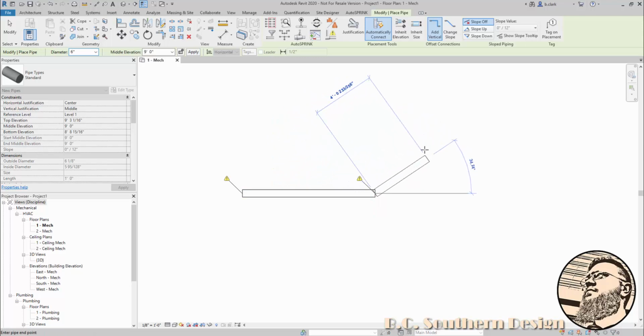One of the nice things about using this approach to control your angle is if you are planning on fabricating some of your own fittings for odd angles, then you can use this to draw those odd angles as well as snapping to the more common ones.